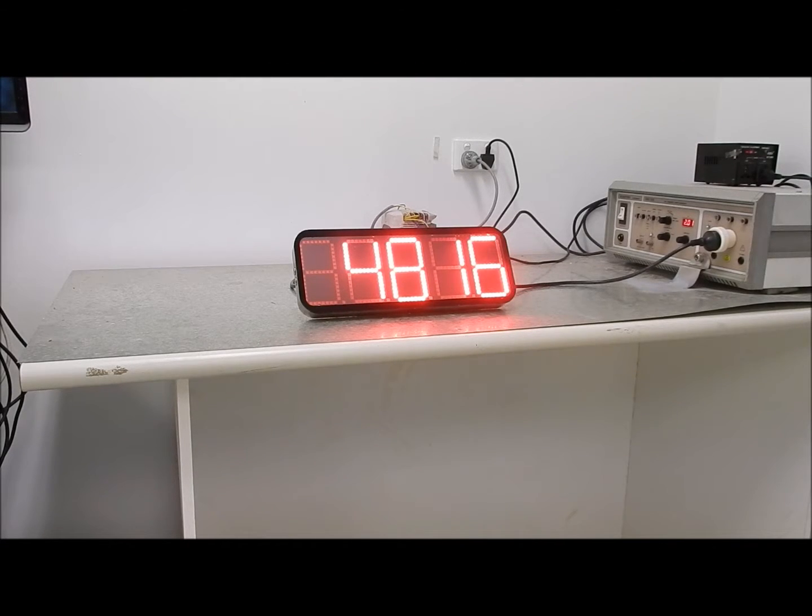We often find ourselves helping customers troubleshoot electrical noise problems on cranes that are causing interference with equipment. The trouble with troubleshooting electrical noise on a crane is that you've never got the gear with you to do it. Nobody carries an oscilloscope to site, and a digital multimeter isn't going to pick up a 5 microsecond spike.